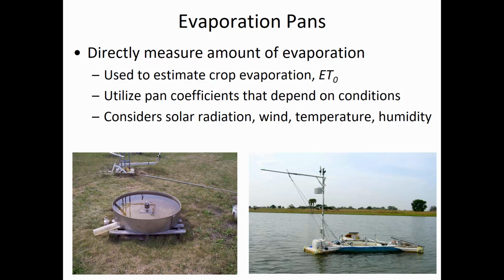You can do these evaporation measurements in open water. This is kind of an interesting contraption where they've got basically a swimming pool of sorts, like a small plastic kiddie pool out in a lake, and they're measuring the decreasing depth of the water inside of that secondary basin there to get an idea of how much evaporation there was for the lake.